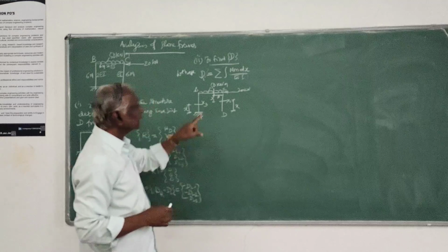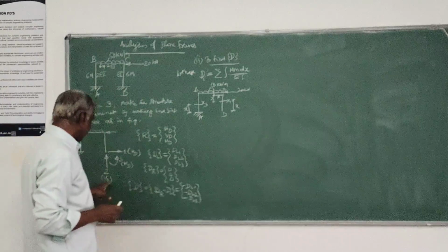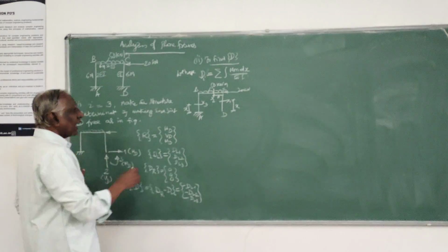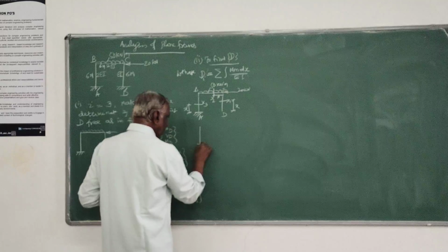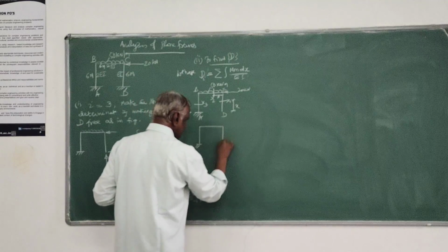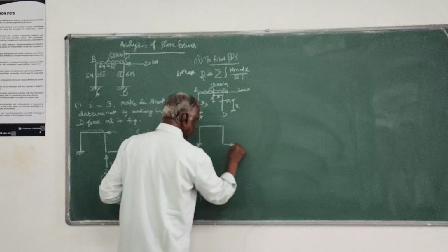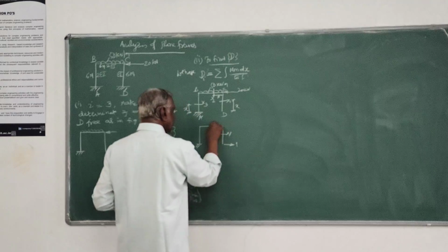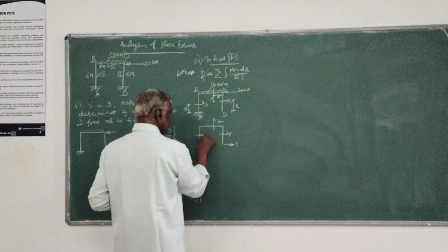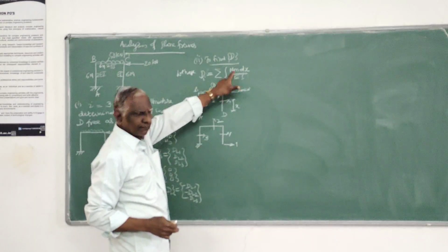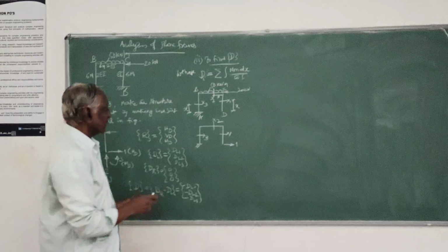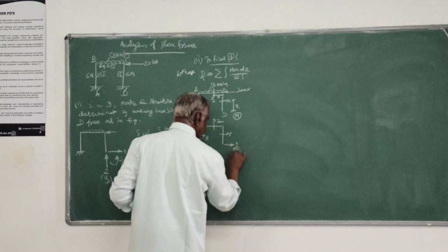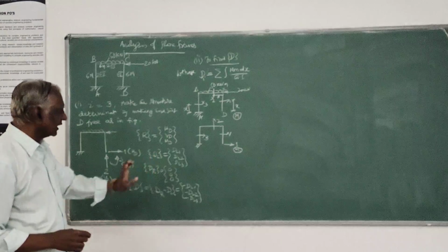Then small m is the unit load moment. I have to evaluate the displacement along each of the coordinates 1, 2 and 3, so I have to apply a unit load along those 3 coordinates. I will apply a unit load here and take the same sections x1, x2, x3 for calculating m to cover the entire structure. This is for calculation of small m1 along that coordinate.